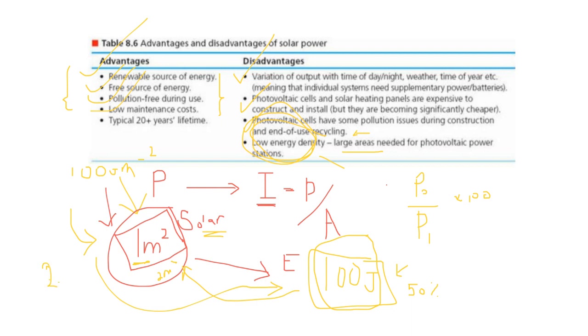If the sun coming in is 100 joules per square meter, you would need 2 of these 1 meter panels to generate 200. Does that make sense? So you work backwards. Work out your energy in using your efficiency and what you're getting out. Once you know that, use your intensity value to work out the area of the panel.